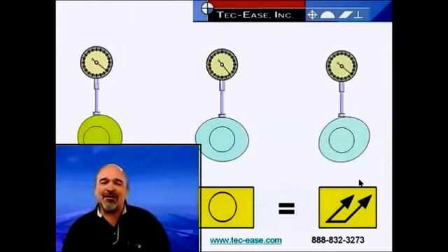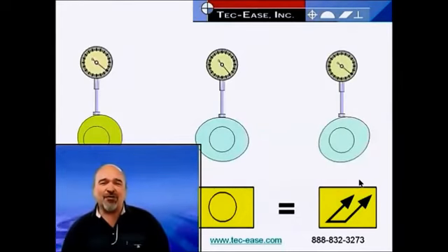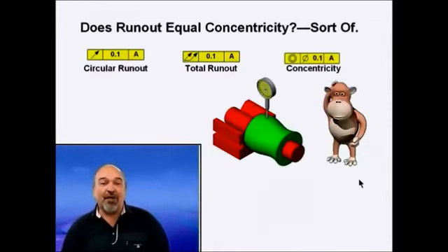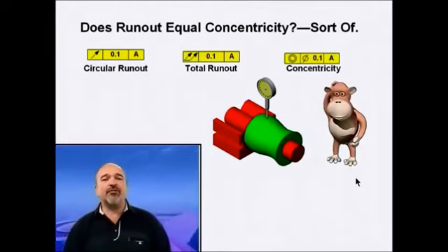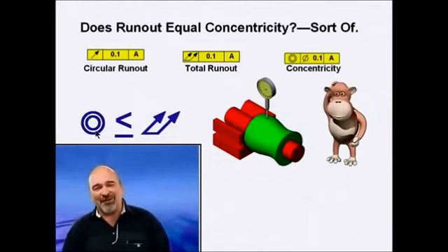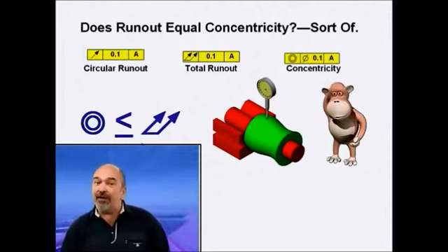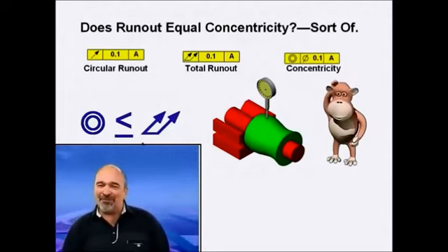The concentricity error must be less than or equal to the measured total runout. So, if the total runout measurement does not exceed the specified concentricity tolerance, the part is good. No need to double the measurement or divide by 2. But why not just forget about concentricity and use runout? It's easier to verify and also controls the form. My philosophy, when in doubt, use runout.